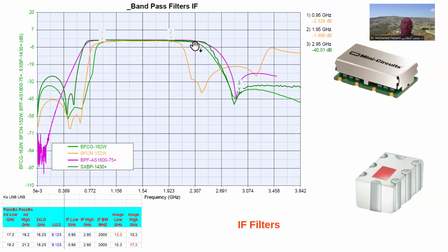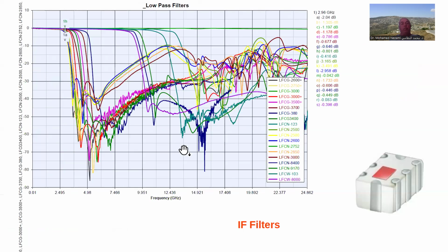You can see that all of these I can't really cover to 2950, but they work beautifully from 950 to 1950, which is the most common. That's what, as you can see here, well, no, this is for the new part I'm proposing. But for conventional low noise block IF converters, usually 950 to 1950, all these filters work really well.